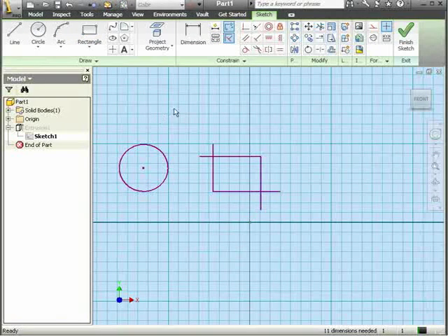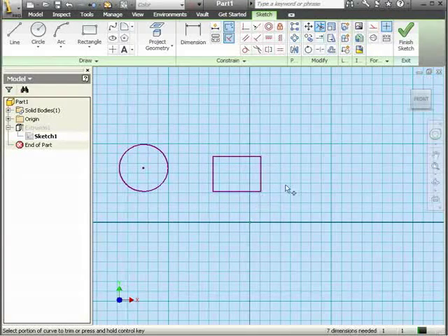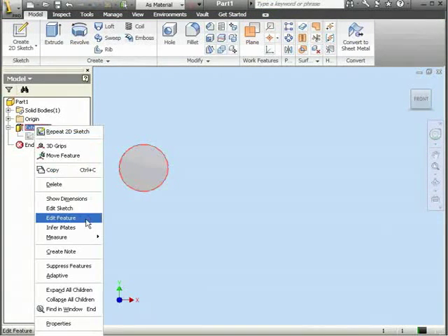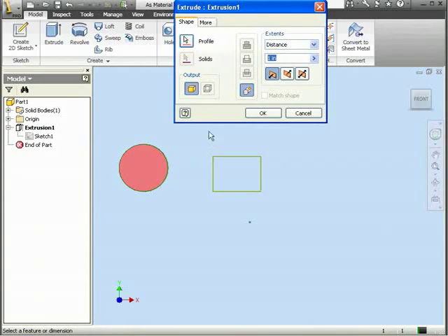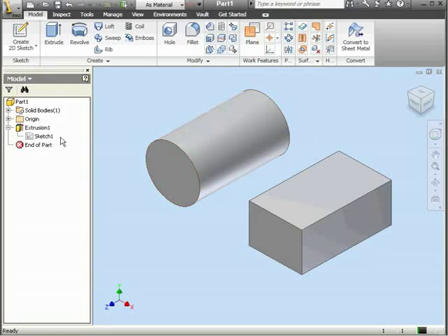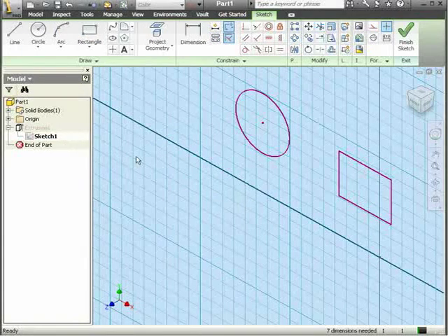Double-click on Sketch 1. Let's go fix our problems. We'll activate the Trim tool. Let's trim these corners and then finish the sketch. Back to Extrusion 1. Right-click, Edit Feature. The Sketch Doctor's red cross icon is no longer displayed. That means that we fixed our problem. Let's click on Profile. We're able to select the second profile now. Basically now we've got two closed loops, and we can use these to create solids. Let's double-click on the sketch now. We'll make some more changes.